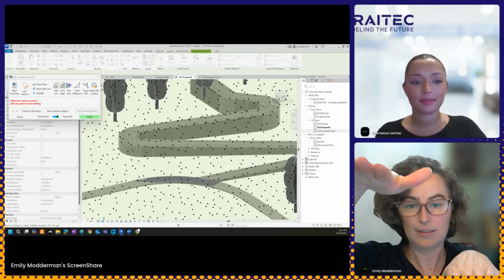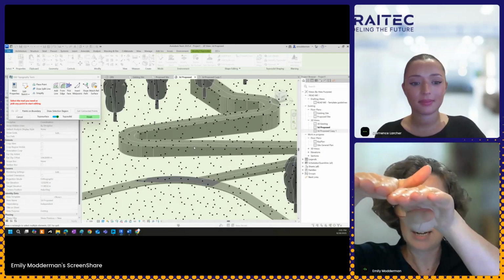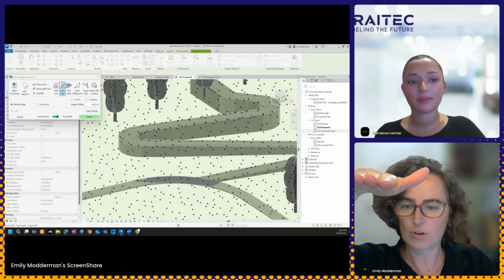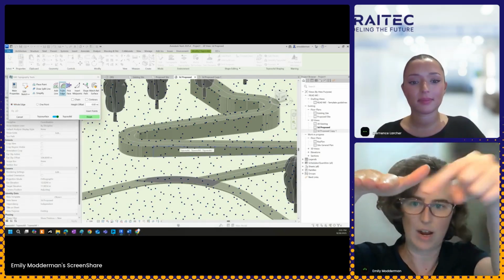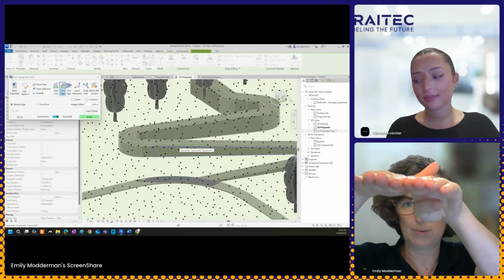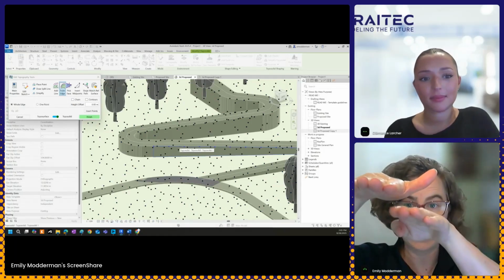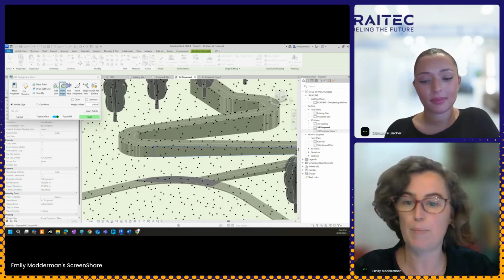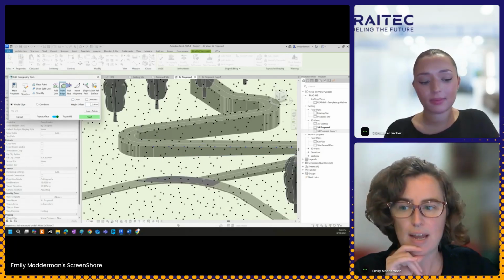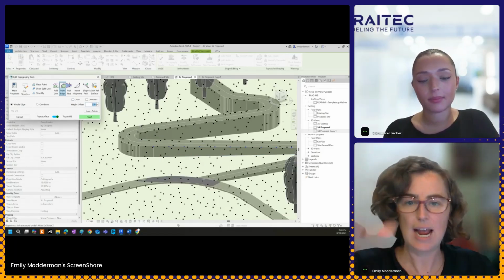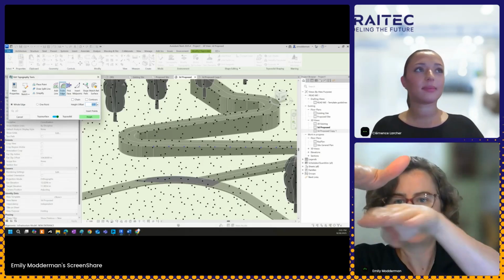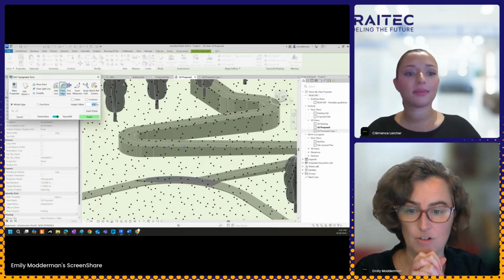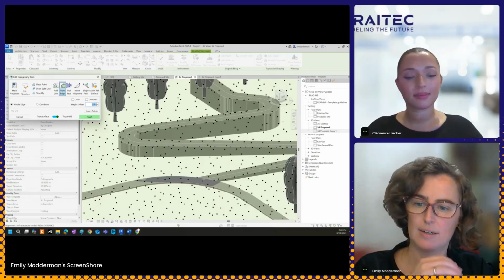If I pick that edge of the top of the surface, it will create points along that new edge, maybe around the sides. And if you don't want it to come right up to the edge, you could pick the underside. Depending on how high your wall is, you could pick any edge and adjust for that height offset. Then it's going to bring your topo solid up to those points, hopefully filling in that edge. So positive or negative offset to set that up.